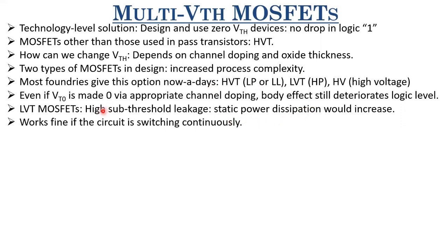However, such a design works fine if it is being switched continuously, because then it's the dynamic power dissipation which is more important. It is not in a static condition for a large amount of time. So if you are making static circuits with this kind of design, it's not advisable. But if you are using this approach in designing a circuit where the input is changing continuously or the output is switching continuously, then it makes a lot of sense to go for this.